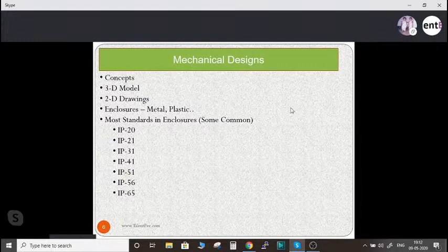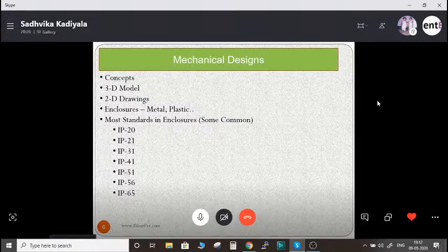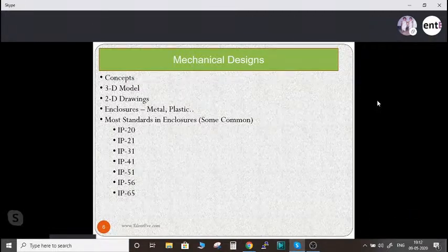My design concepts are the same. The only thing I need to bother about is the particular domain knowledge, which I will take up. I will go into that particular area and work it out. Let me give some examples from defense. In the aerospace sector, your specifications are normally much more stringent. If I go into aerospace electronic product development, the basic frequency itself is 400 hertz, which is the highest operating frequency, while industrial products, automotive products or energy utility domains all work at different frequencies.